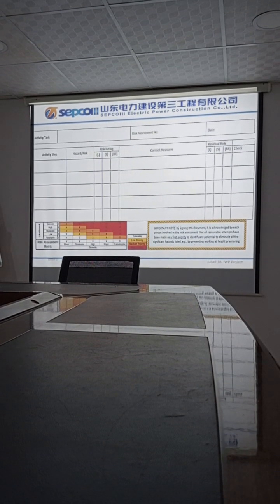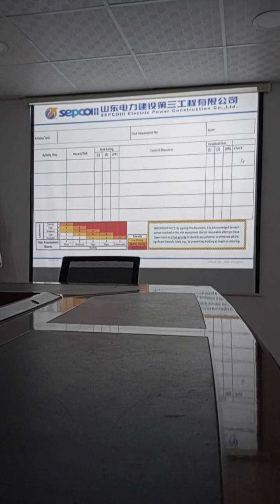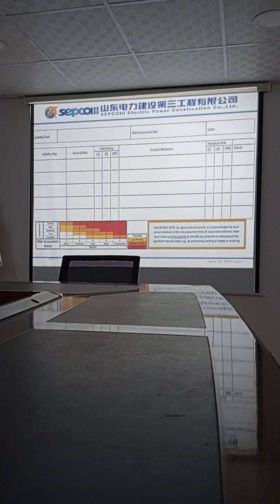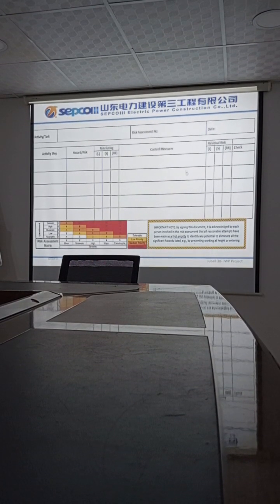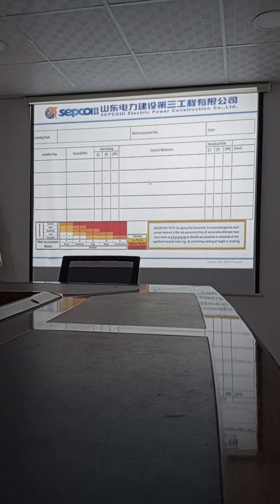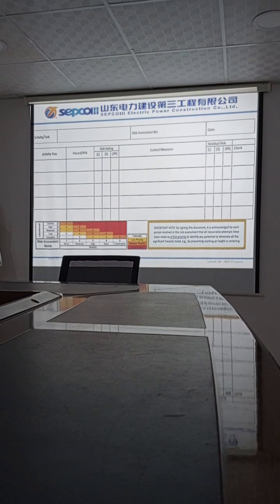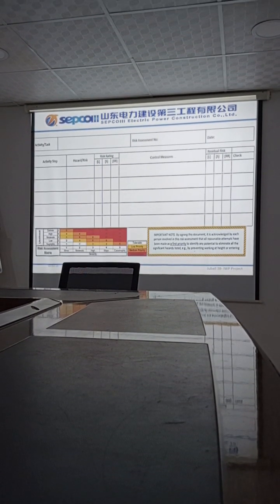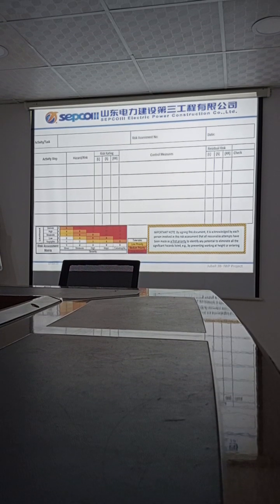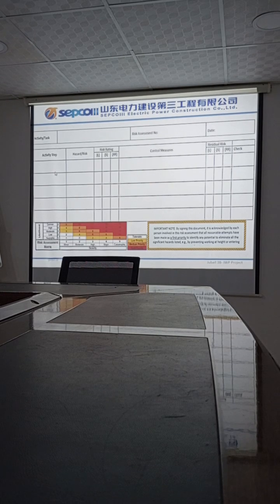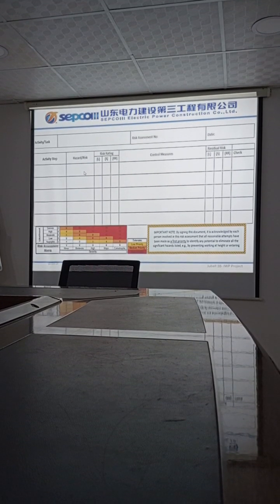And who will check this? Myself or the office boy. If responsible by the foreman or engineer, then he is the one who should check the control measure. That's why all information taken here should be understood by the permit receiver. Why? Because you are the one receiving the permit and you need to check this control measure is applicable outside. For example, painting, and your hazard is fire.